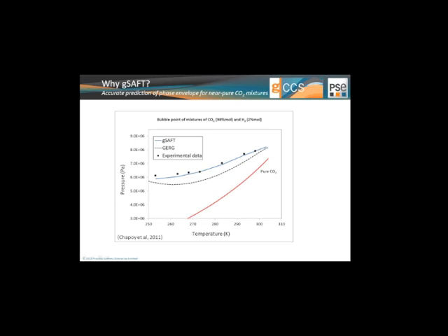Now, if we look at something that has been adjusted for similar mixtures like GERG, arguably this is not for the high CO2 purity end, but more on the methane side for natural gas mixtures, but still has been extensively validated for mixtures including all those components. We'll see that it still shows a mismatch of about 5 bar in the relevant region for the vapor pressure. And this is exactly where we feel that the gSAFT or SAFT technology that we have acquired closes the gap, as it's able to predict the impact of impurities quite accurately.